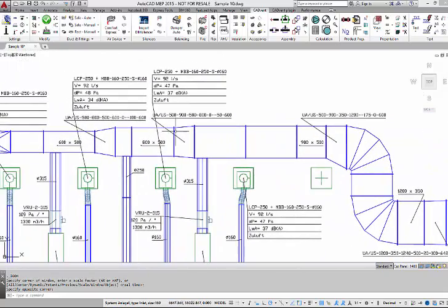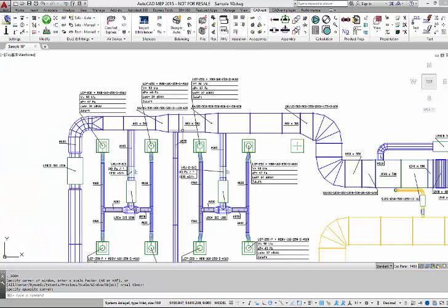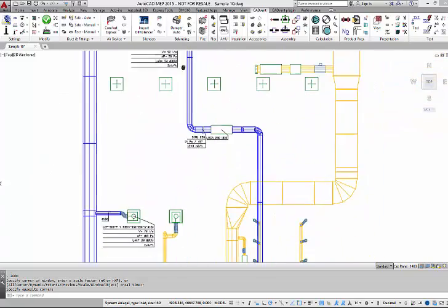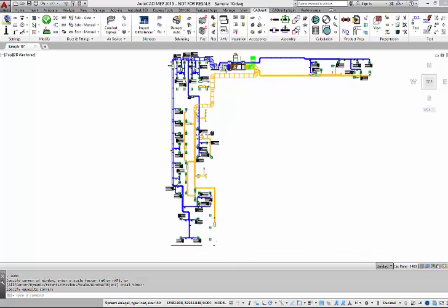For example, I have a full texting here. That means all the diffusers get a lot of information like flow, damping. You see this is 47, 48 Pascal. Everything is balanced here. The sound levels we have here, it's the sound power levels, by the way. So don't wonder that we have 37 decibels. So you can choose whatever you want in the texting based on variables.